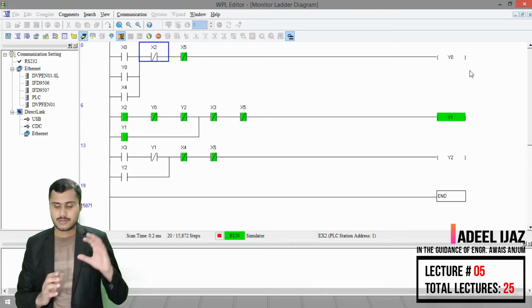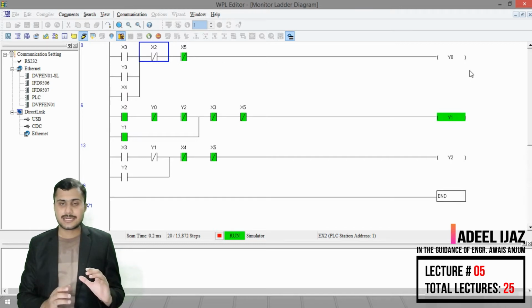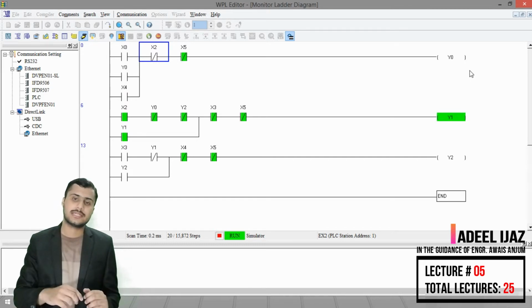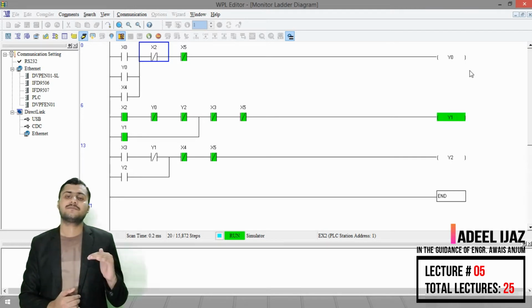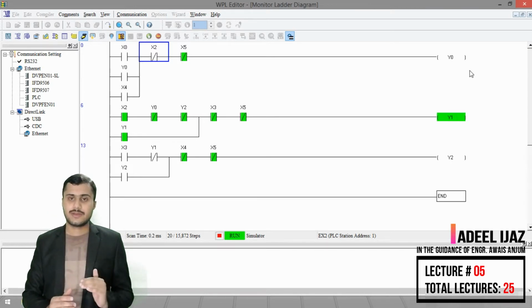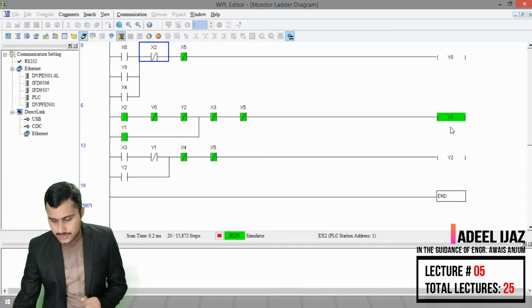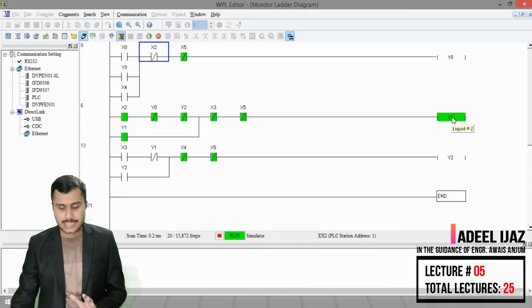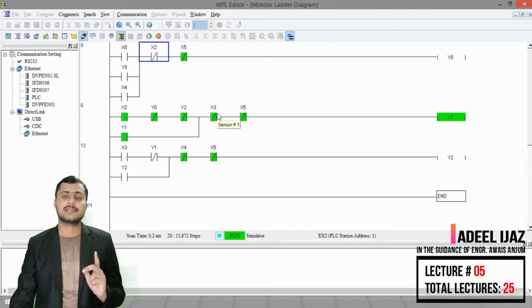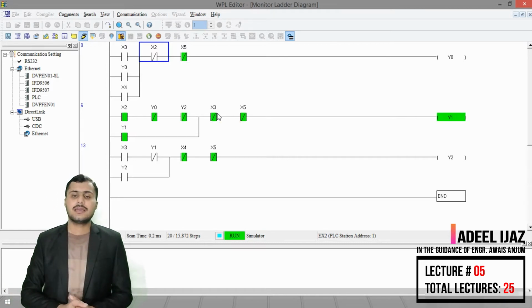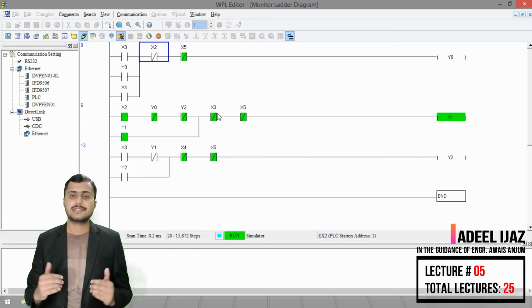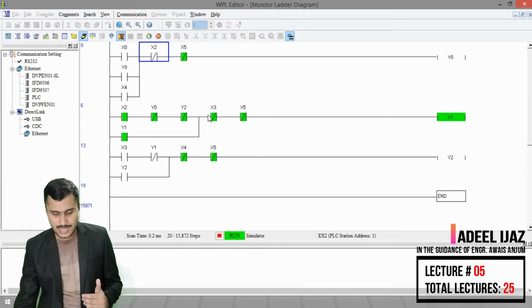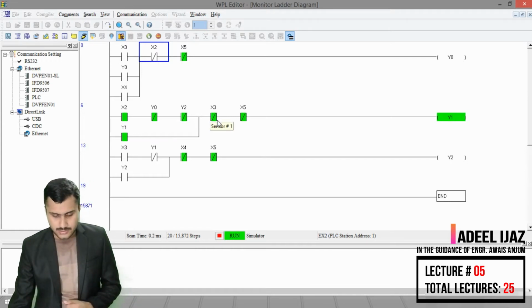Now liquid number 1 was already present in the tank, and liquid number 2 started to flow in, so the volume of the liquid will increase. In case of increasing volume, our liquid level will rise. So liquid number 2 will continue to enter into the tank until our X3, which is our sensor number 1 attached on the top of the tank, gets activated. So let's say our liquid number 2 reaches the level of sensor X3, which is our sensor number 1. So when this activates,